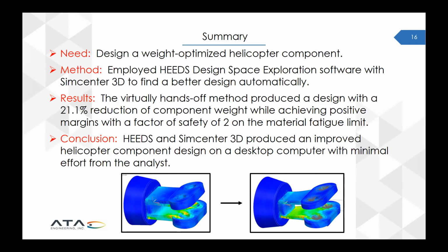Yeah, I've got a question. I have run a number of these types of stress optimizations using Simcenter 3D and also other software tools. And oftentimes I will find that the optimizer focuses on unrealistic stress hotspots that are just an artifact of the discretization that an analyst would simply ignore. Can you comment on how to avoid these stress hotspots in corner regions where a fillet may not be appropriately modeled, or those types of things?